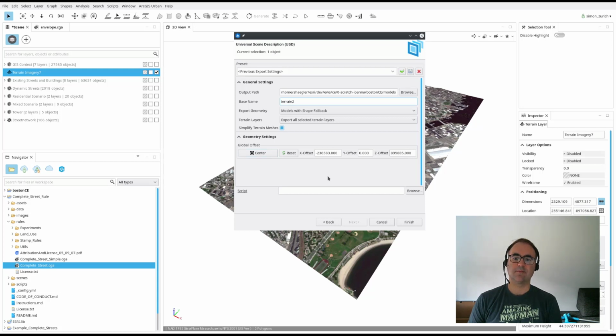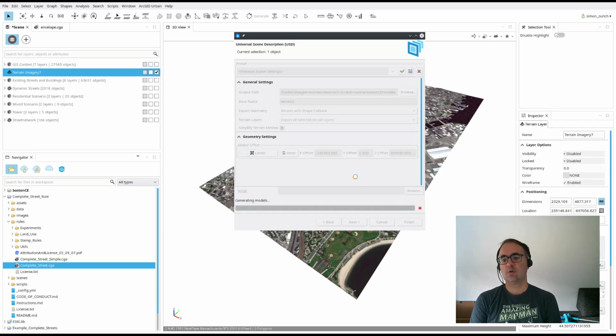Here we will center the exported geometry around the origin to prevent precision issues in Houdini. It is useful to round the offset to the nearest integer and reuse the same offset in future exports so that everything aligns within Houdini.